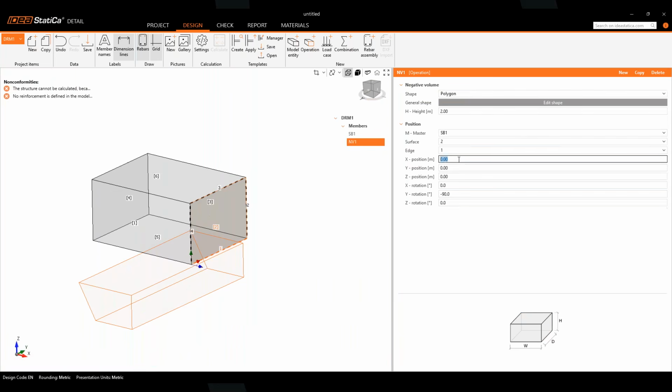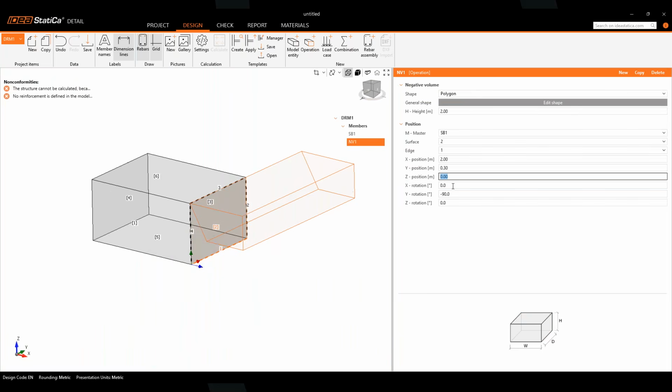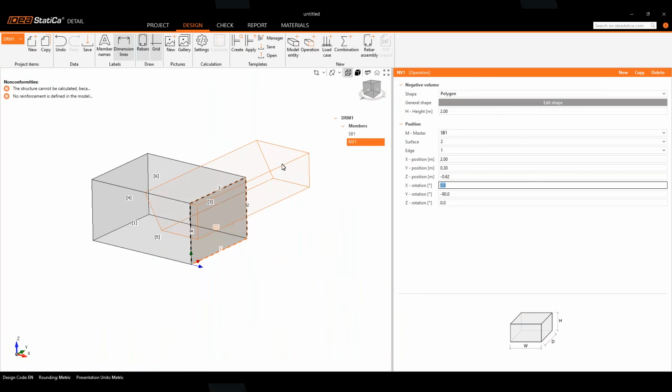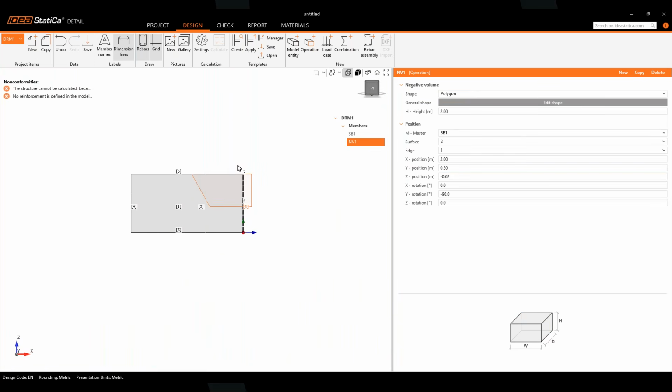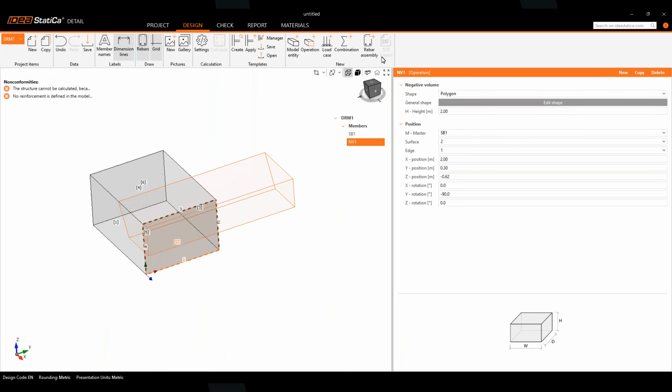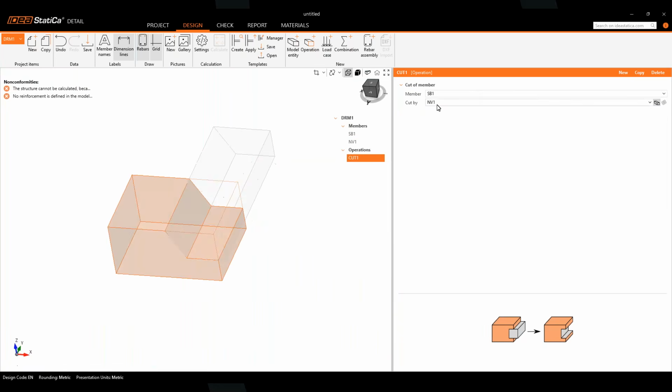And then the X position to, let's say, 2, it should be done. And the Y position to 0.3, I want to move that up. And then under rotation, and then Z position, -0.62. So here, you can see this is the shape of my negative volume right there. From here, I can basically click on operation and click on cut. You can see it's already cut now.